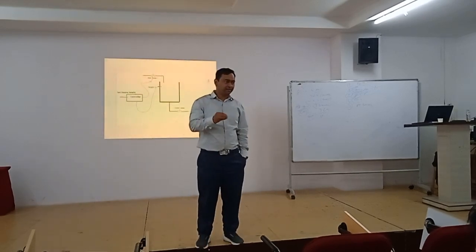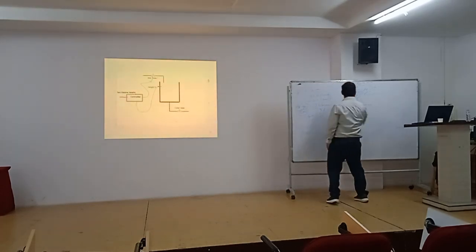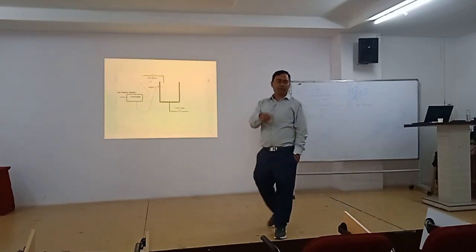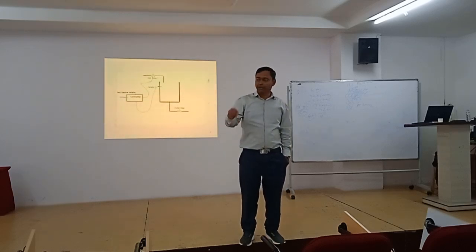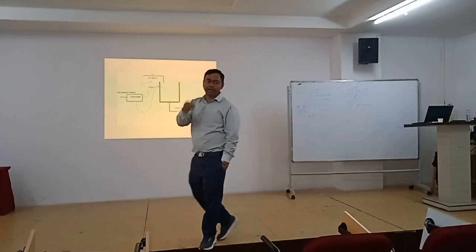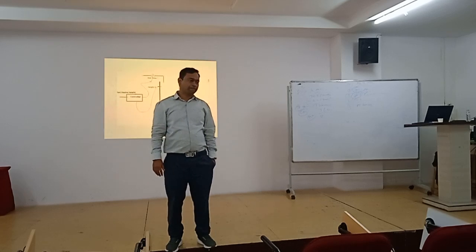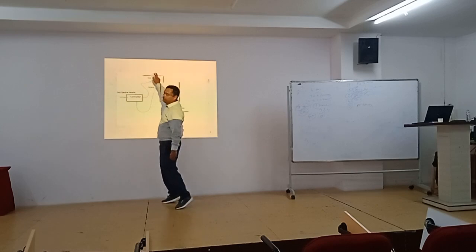The reason is, whatever controls you have discussed, apart from the first one, all are electronics based. All are electronic controllers. Whenever you talk about electronic controllers, they are very poor in power output, or very poor in power delivery. So directly they cannot operate this valve.